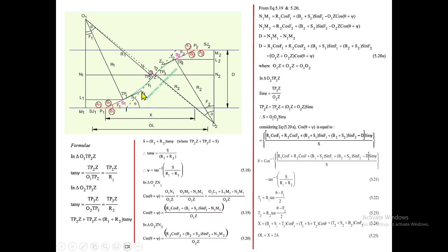Okay, first triangle we take here, B1 S1 is there, you can add S1 also, and T1 cos F1, we got up to this point. Then T1 here plus S, and T2 cos theta will be your horizontal distance up to this point we come. Then we can go from here T2, S2, B2, cos F2, this is F2, this is also F2. So we have come up to this point. So adding all, we are able to get the x distance. Once we know the x distance, adding A1, this side A2, we'll be able to get the overall length.